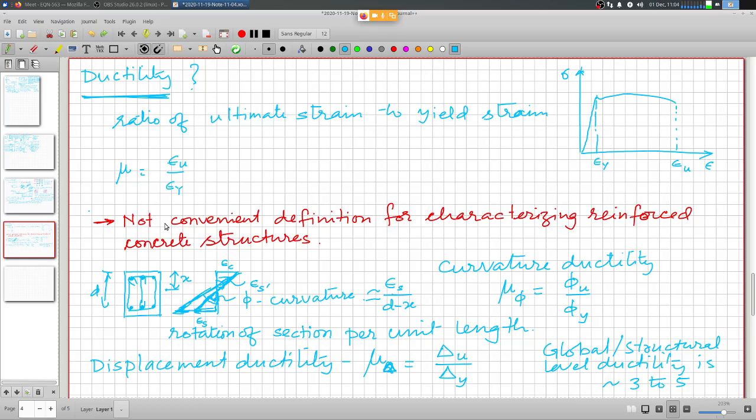So you need to use ties of sufficiently higher diameter and also at a closer spacing, whichever allows you to work with the bending as well as avoid the yielding of the stirrups or lateral ties during the alternating direction of shears during earthquake loading.